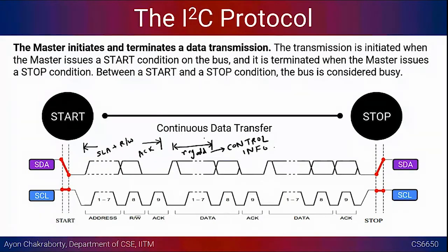Let's say in this sensor you have n memory locations, and you give the first address and then keep on putting data on the data bus. The device will write the data in that address and then keep incrementing the address by 1 every time a new data byte arrives, right?